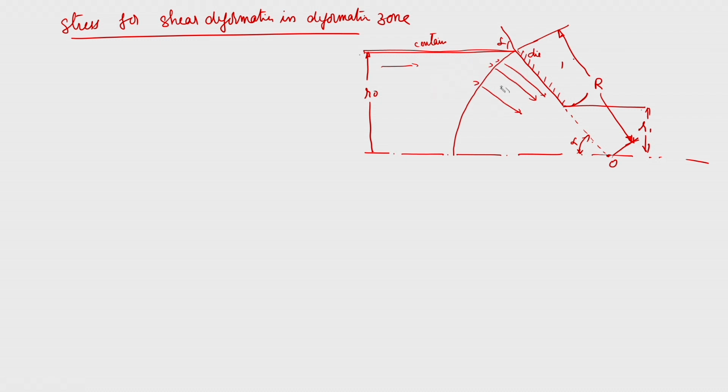So, there is going to be a velocity discontinuity when you cross this region. This is the discontinuity surface, which is shown by this. Across this surface there is going to be a non-homogeneous shear deformation, and the energy and the load necessary for this we have to estimate. Similarly, when it comes to the exit, here also we are assuming there is another velocity discontinuity, because after this it is assumed that there is no metal flow in the initial direction.